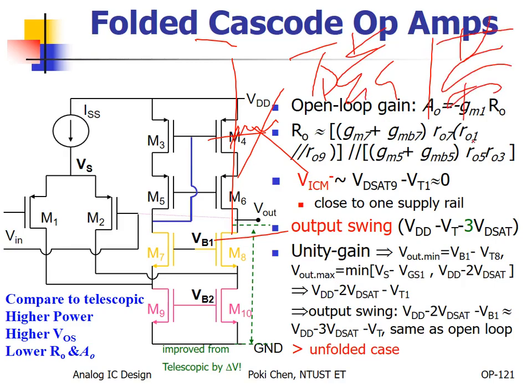It means from here to there, above it, change to the other side. But from the top to the bottom, here, then change to the lower side. That's it. So in the middle, that is the so-called hysteresis. It can help you to prevent the circuit from oscillation or unstable operation.